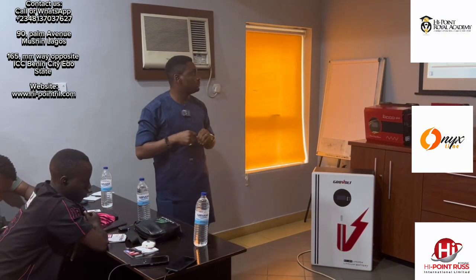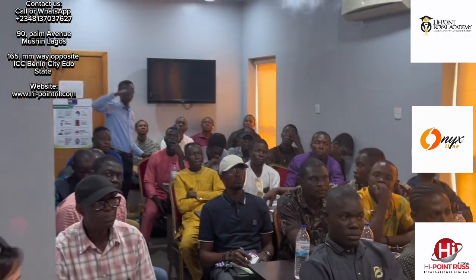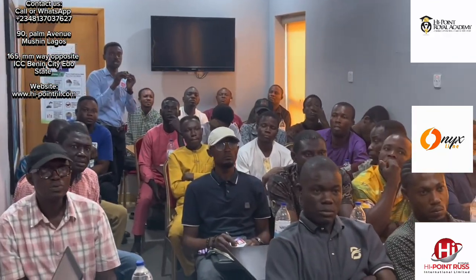If you notice, what was shown in that picture was just both charge controllers. Can we have that picture back on, please? If you notice, both charge controllers just connect to the bus bar. The bus bar is actually the battery bus bar. The entire battery system was connected on that bus bar. The inverter took from that, and the charge controllers are also sending their energy to that.